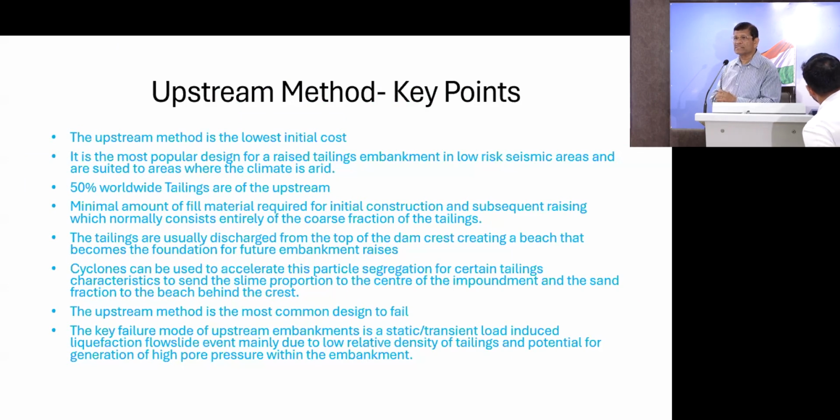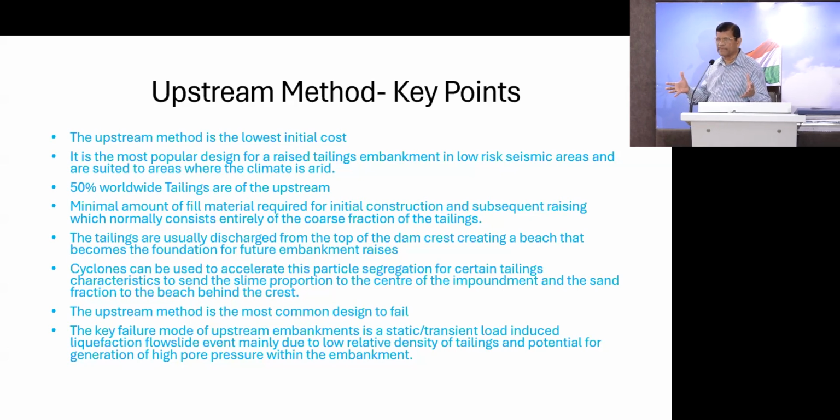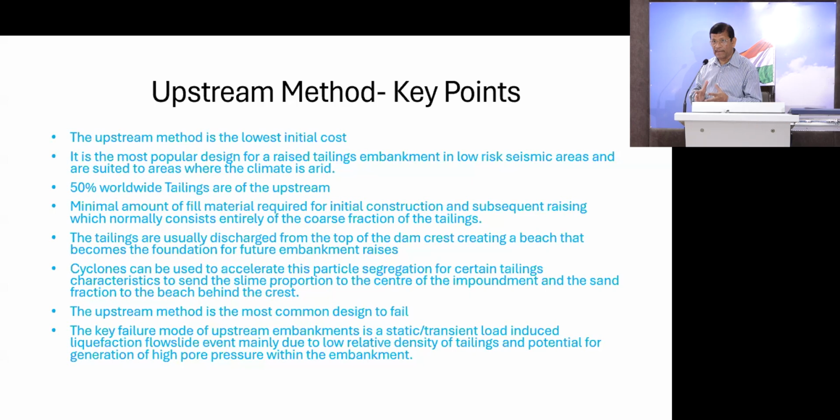What is the advantage of this upstream? This method has the lowest initial cost, because we are just doing a small starter dam in the beginning. The starter dam is hardly more than 100 feet in height. The starter dam, the beginning dam, is the cost of the things. The rest is just storing, because we are again using the tailings for the construction of the dam, like the sand part, and then the finer part goes to the ponds. It is very good in low seismic areas.